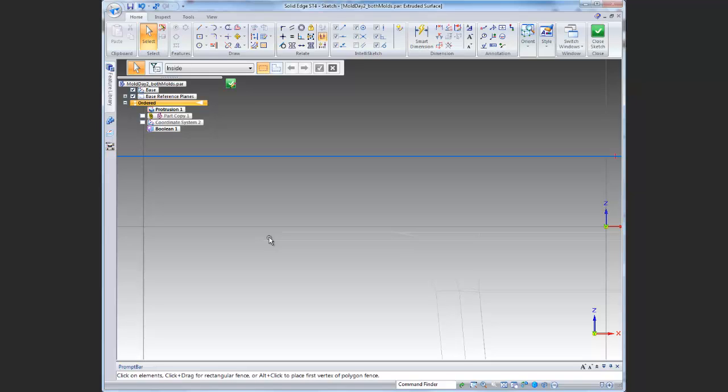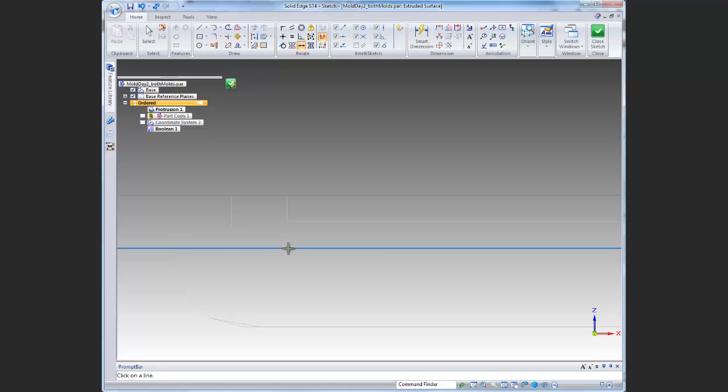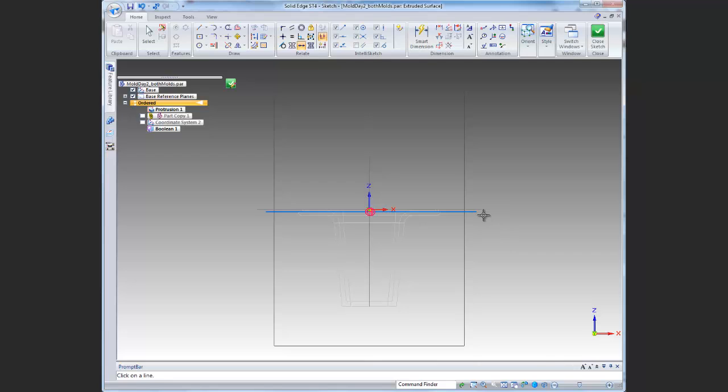A couple ways you can do it. What I'm going to choose to do is add a collinear relationship. So I click collinear and I say make this line collinear to this line. There's a lot of lines in here, so make sure you get the right one. So this line collinear to this line. Not sure if that helped any by zooming in, but that guy. So it snapped it down. The length on the outside doesn't matter, just make sure it goes beyond the box.